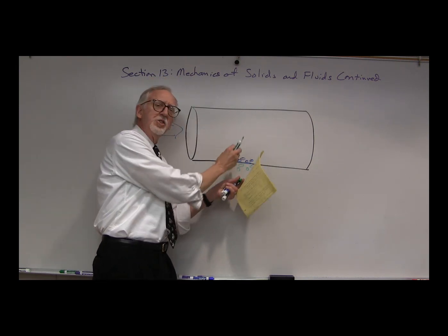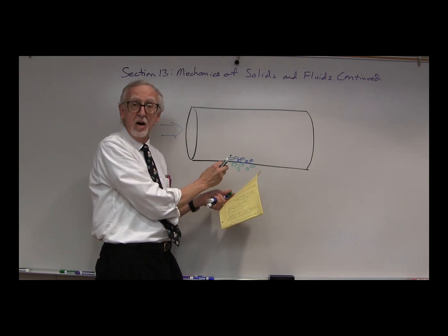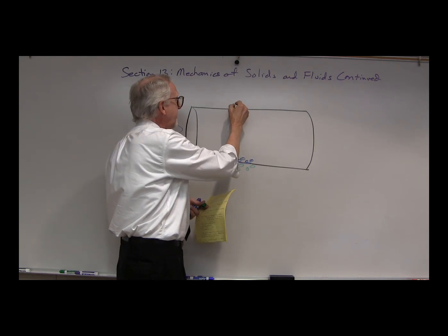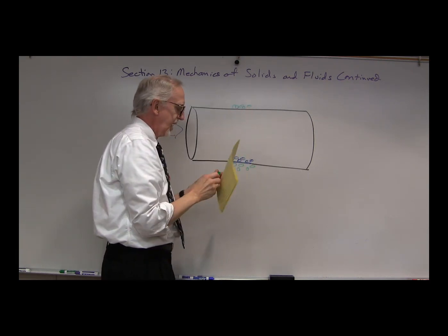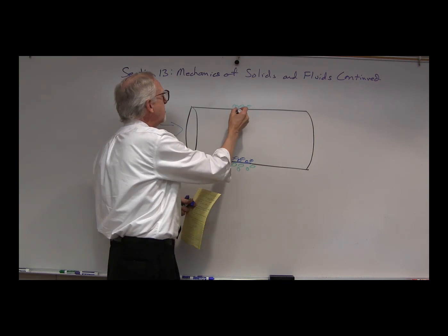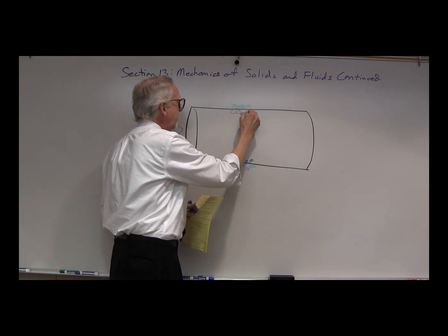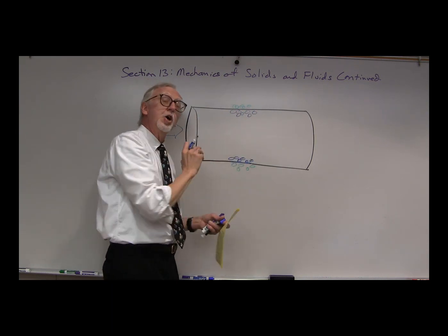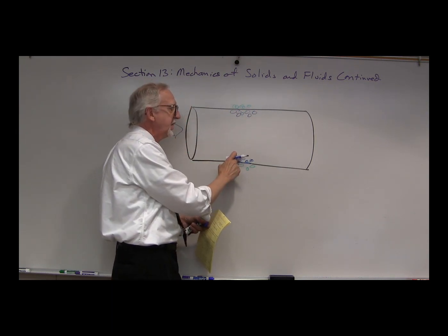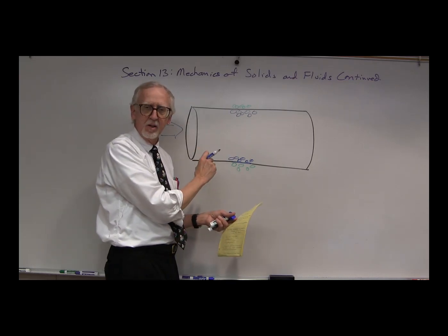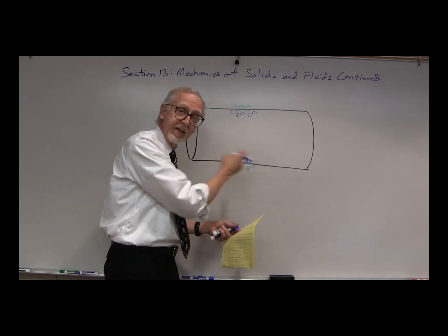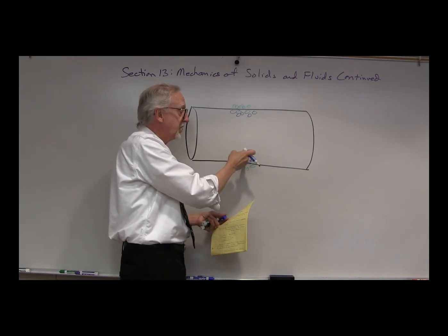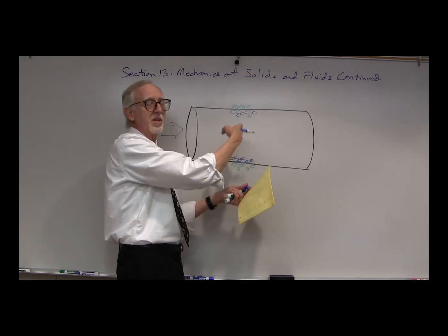So that's going to tend to slow down the motion of the atoms and molecules of the fluid near the wall. So down here and then up at the top surface, we're going to have some forces of attraction between the fluid particles up here and the walls. That's going to slow down these. And then the cohesive forces between these atoms and molecules that have slowed down are going to slow down the ones next to them. That's going to have an effect on the fluid that is close to them, which will have an effect on the fluid close to that, and so on.